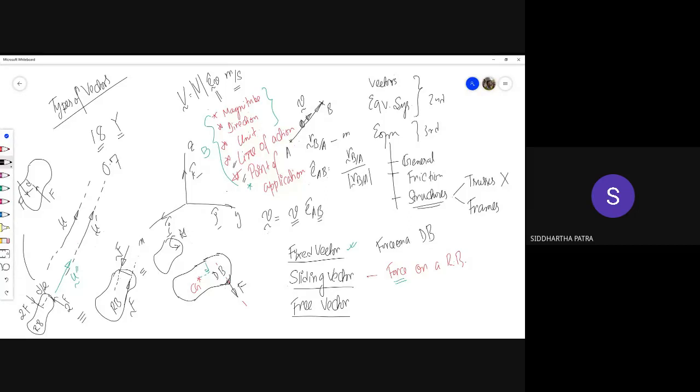The fun fact with the couple moment is this, that this moment is essentially the moment due to the positive F force and the moment due to the negative F force. Now the question remains about which point. The answer is any point. That means you could be taking the moment about this point or the center of gravity or anywhere outside in the space of these two forces individually and add them up, and the net effect is going to be this couple moment. So it doesn't really matter where exactly the force is acting.